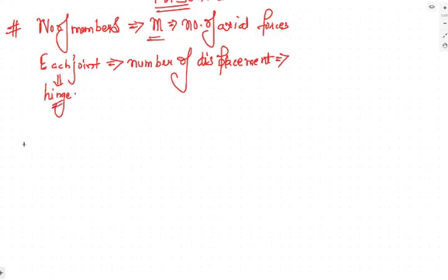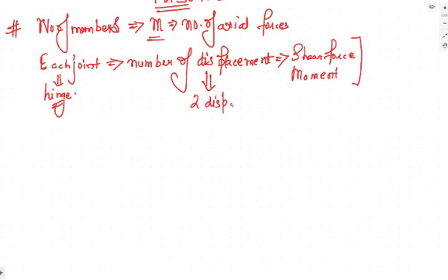Axial force develops on it. So the hinge can stop the axial force, but it cannot stop two things. One, it cannot handle shear force, and also it cannot handle bending moment. It can be the case that at each joint there can be two displacements, two types of movements. Let's say there are j number of joints, j is the number of joints.